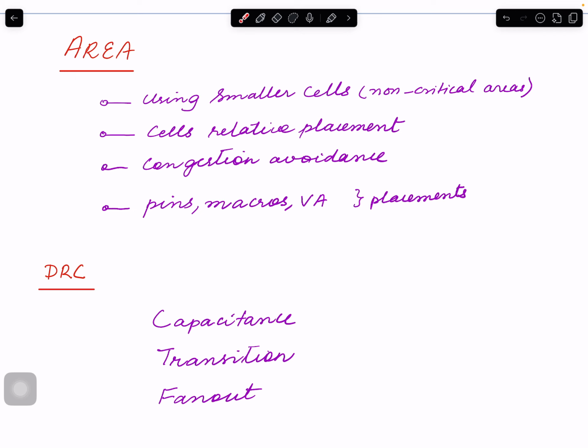But at the same time, if your design structure is such that you have a lot of wiring going on, keep in mind that wiring is also going to be in the similar area, and a certain area contains a certain number of metal 1, metal 2, 3, or whatever metals you have. It contains certain routing tracks, places where each metal can go, and that is also constrained.